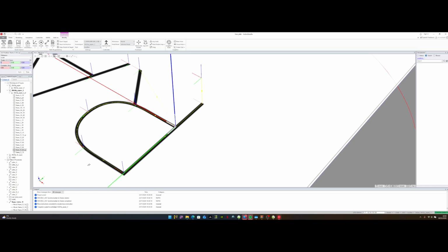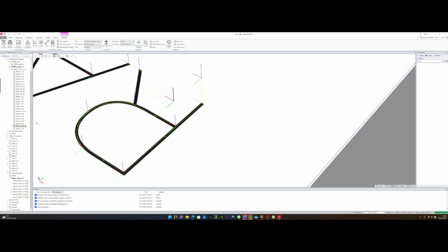In the modify target set position, I'm going to change update. Okay, reference frame, one sec. Yeah, X, Y, and Z, right? Yeah, so this is the Z-axis. So I can change this to 15 and apply. And now it's going to be up 15. So I've modified it this way, okay? Close. So now we have another target here.